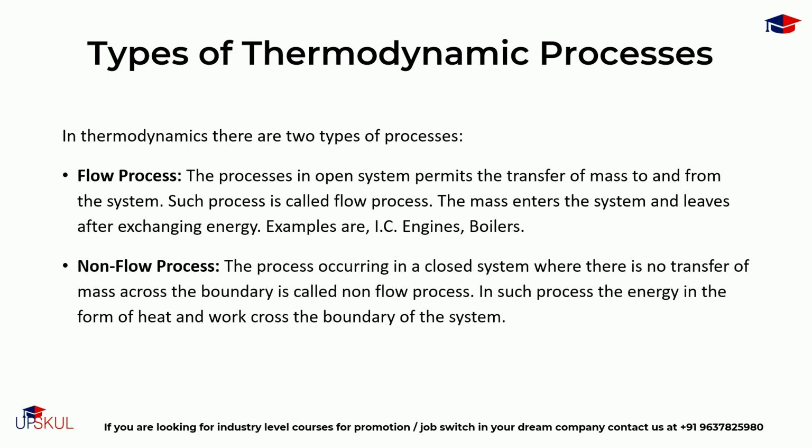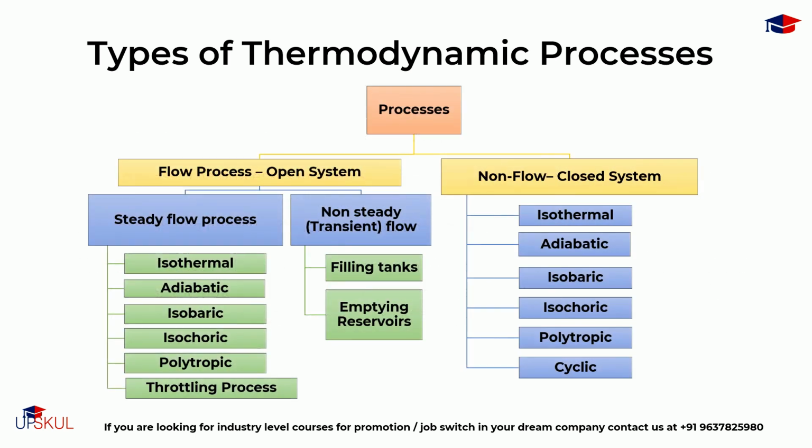For non-flow processes, the process occurs in a closed system where there is no transfer of mass across the boundary, and in such a process, energy in the form of heat and work crosses the boundary of the system. This is the complete classification of thermodynamic processes.